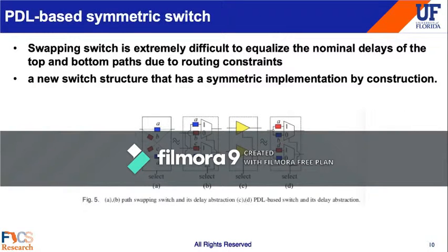So we introduced the PDL-based symmetric switch. The old swapping switch makes it extremely difficult to equalize the nominal delay of the top and bottom paths due to the routing constraints shown over here on the left.